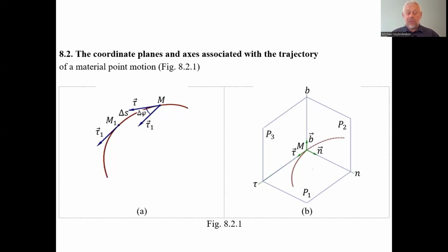And having these two axes, the tangential axis and the main normal axis, we can find as well the perpendicular binormal direction and the so-called straightening plane. This is the plane in which we have the tangential direction of the axis, and at the same time it is perpendicular to the normal plane, or perpendicular to the osculating plane. This is the so-called straightening plane.